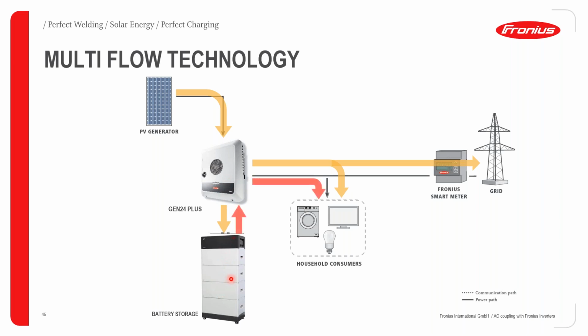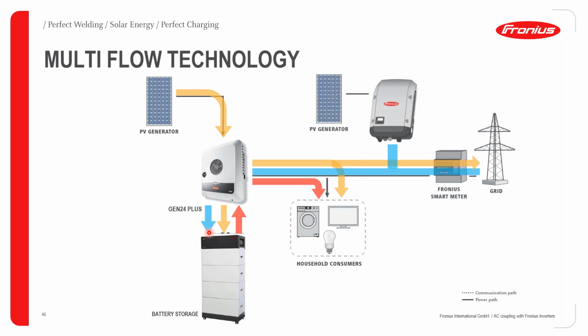And then we can achieve DC to AC conversion, that is, convert the DC power from the battery to AC to supply the load. And with the availability of the grid, you can also charge the battery directly from the grid, with the inverter converting the AC to DC. And then you can have it retrofittable, depending on your choice and capacity, and the DC to AC ratio of your PV module capacity.